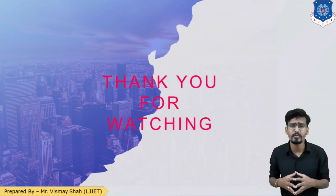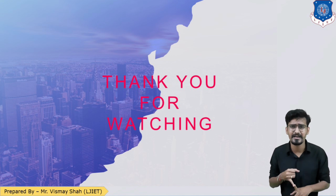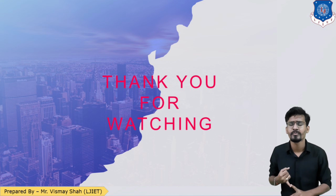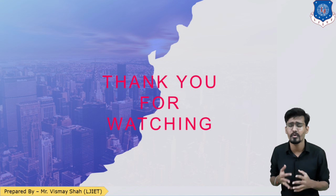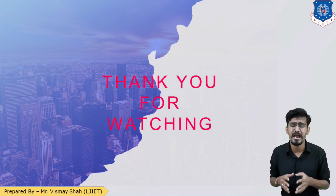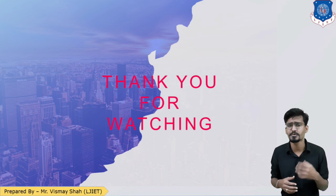That was all for today's session. We have learned 5 concepts of the CPM method. What is the CPM method? It was invented by DuPont and Remington Rand Corporation. It is activity oriented. It follows a deterministic approach, in which you know enough information about the activity so that a single time estimate can be represented. Then we have seen earliest event time, latest event time, and 4 activity durations, applications of CPM as well, and the questions whose answers we can find using the CPM method.